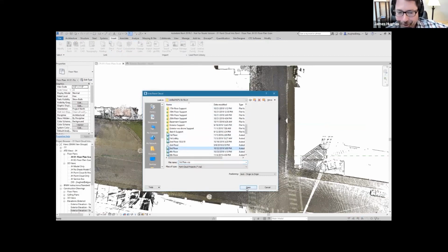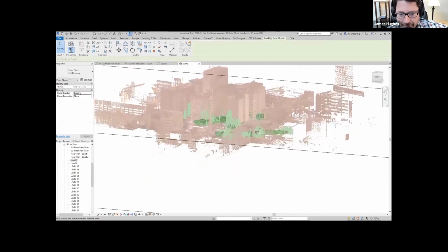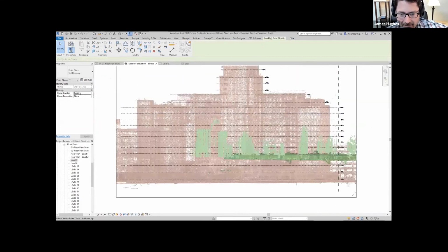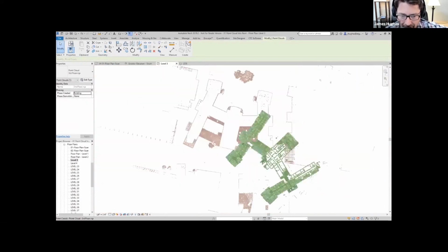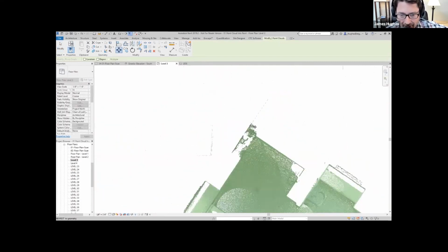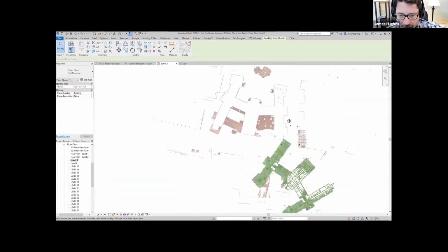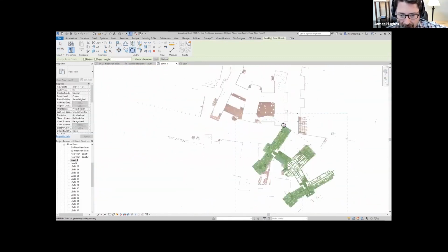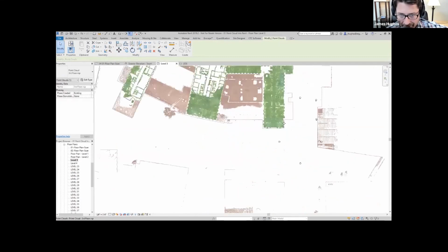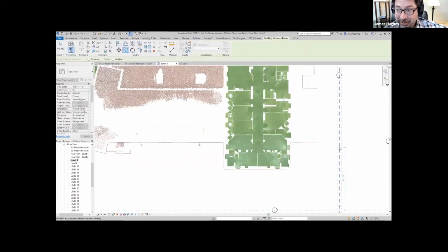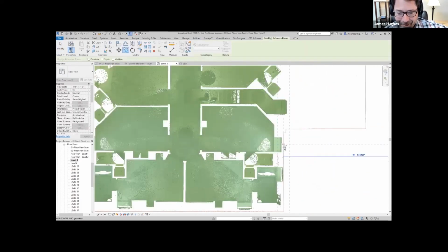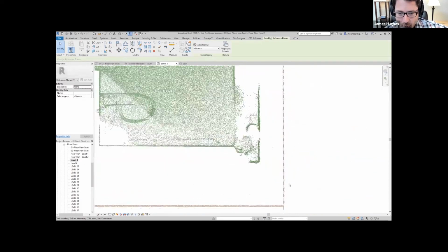So we'll put in another point cloud too. This one's on the interior of the 3rd floor. And if you see it in 3D space, it's elevated wrong and it's rotated wrong. So I can just zoom in, grab the floor of that, drag it roughly down to level 3. I can see it spun out. And so I can move from one precise corner to roughly where that corner occurs, and then apply a rotation really roughly. That is not how we laid out Charity. I just played that one fast and loose. But you get it oriented.